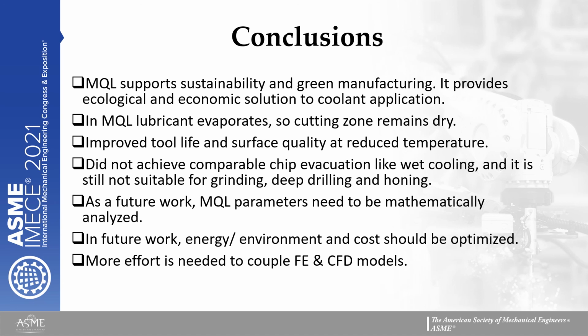It did not achieve comparable chip evacuation like wet cooling, and it is not suitable for grinding, deep drilling and tapping operations. As future work, MQL parameters need to be mathematically analyzed. Another future work is that energy, environment and cost should be optimized for the MQL process or MQL variants, and more efforts are needed to couple the finite element and CFD models for more reliable results.